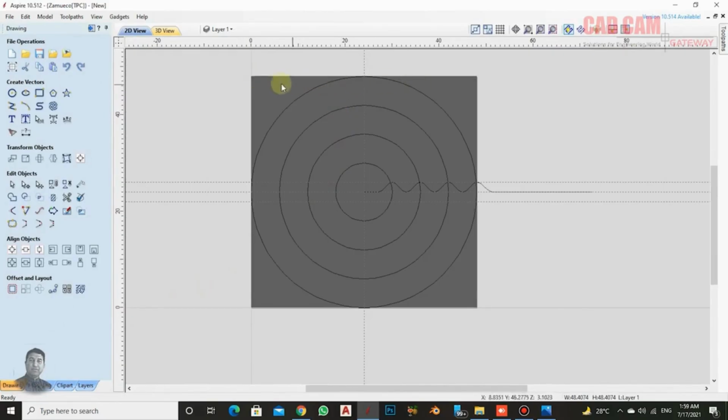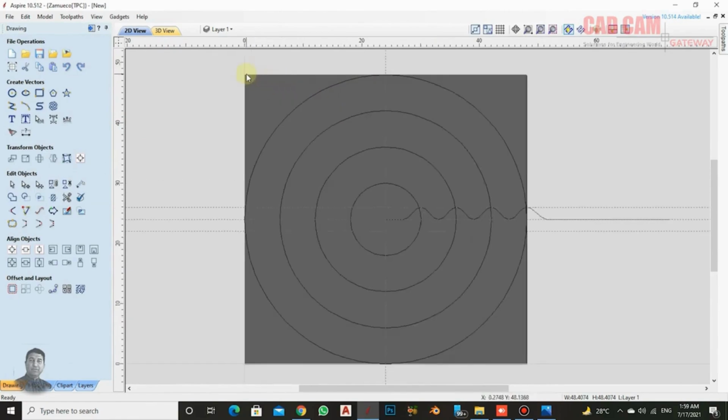Now, what we need is to decide the gap for slicing this design. Look at the gap. Usually, the thickness we have is a 1/4 inch sheet. So if we have a 1/4 inch sheet and then a 1/4 inch gap, then another 1/4 inch sheet and then another 1/4 inch gap, and so on. So if you want to create a design like this, what does it mean? It means that when you slice it from here, there should be a 1.5 inch gap in between.